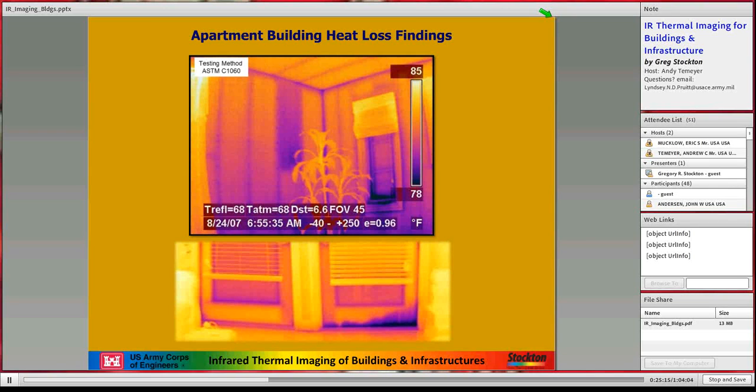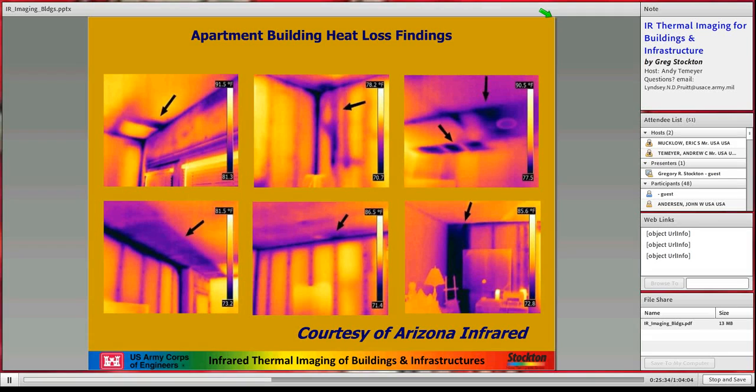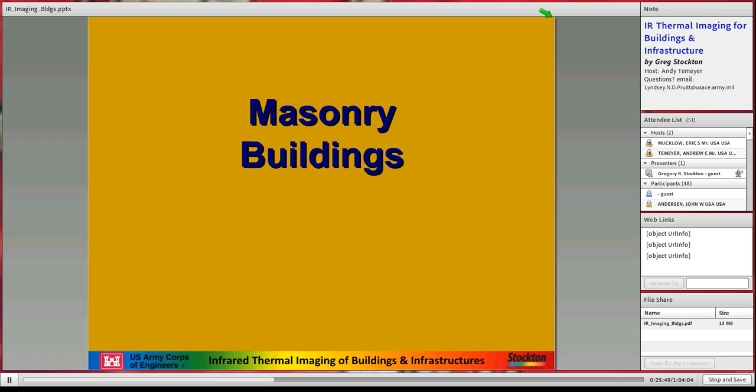A lot of times, when people are complaining, especially very old people in nursing homes and places, they're sitting down in the coldest part because the air is stratified. They're sitting down in the coldest part of the building. So if you just blow the air around well, you'll end that problem. You always see missing insulation whenever fiberglass batts appear. Fiberglass is a particularly bad insulation given its low R factor per inch, but it's an easy installation, and it still gets messed up quite a bit.